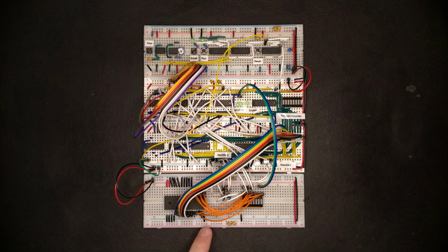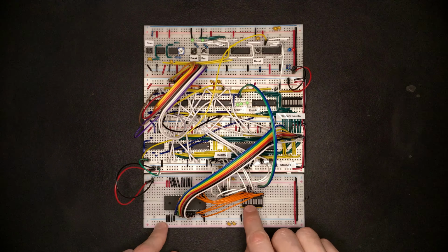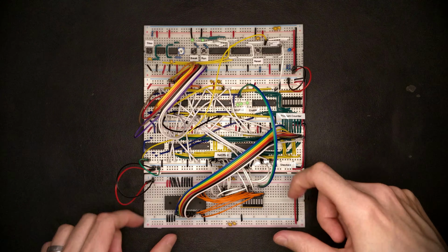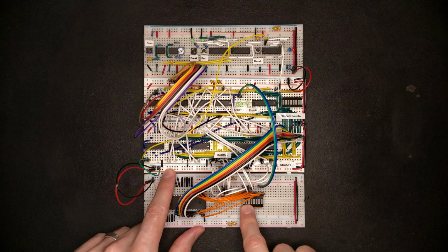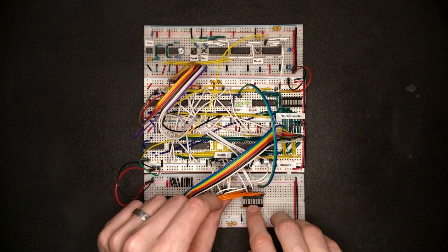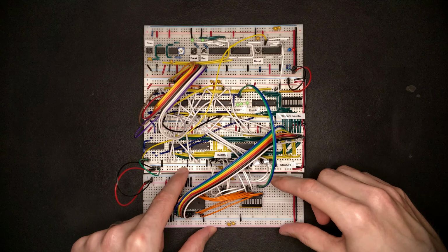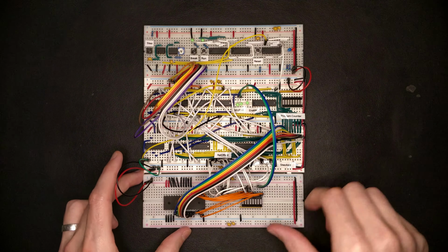And what this will allow us to do is, by programming the upper 4 bits of whatever's in memory, we can control what the program counter sees as the relative jump offset. We can interpret these as signed numbers, such that whenever there's a negative number here, we're able to produce the same negative number as the relative offset because we've sign extended the value.